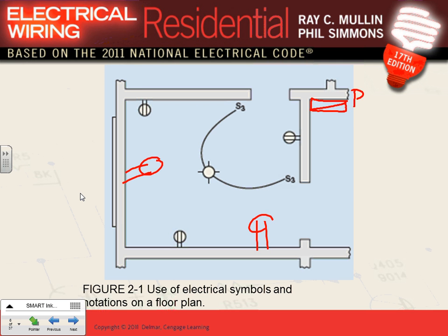Step one, we do spaghetti, we call it spaghetti, in the residential. In commercial and industrial, we don't do that. But I want you to do spaghetti for one reason, because I want you to understand how the system is put together, electrically speaking, wiring speaking. So let's try it. I'm also going to put another can. Here's one can here, another can. So I have 5 lights in this room. I overkill, don't ask me how many. You need at least 1 light by code. I decided to put 5 in this room: 4 cans and a surface mounted light in the middle of it.